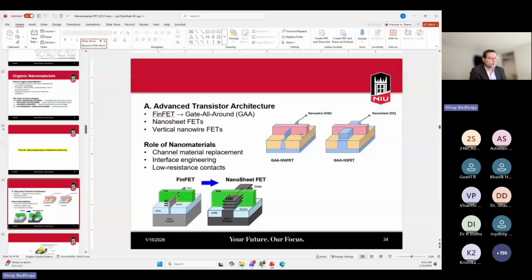In the figure you can see that in the FinFET, we have a gate, source, and drain, and this way we can have only one source and drain. With the nanosheet FET, we have the advantage of having different nanosheets in the vertical direction, and that's how you can control the CMOS technology with one gate. That's why the name is gate all around, the gate all around those nanosheets.